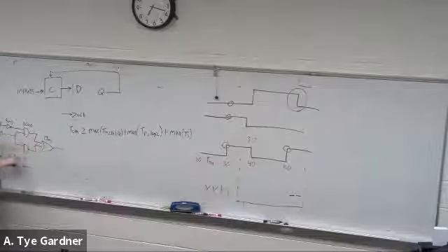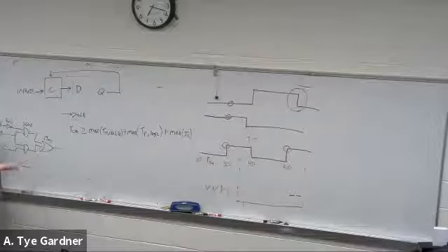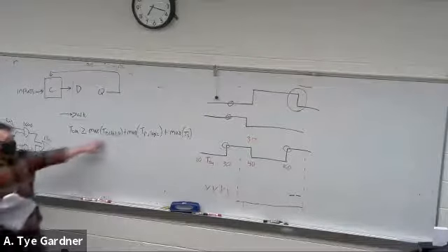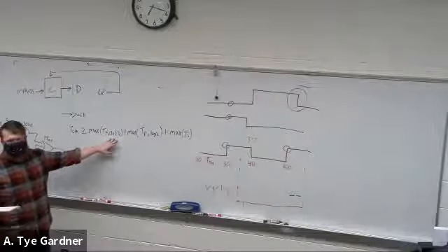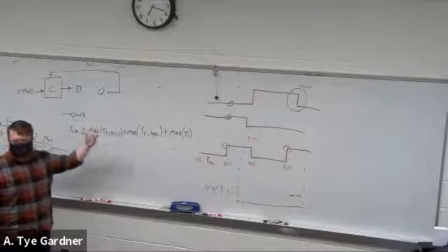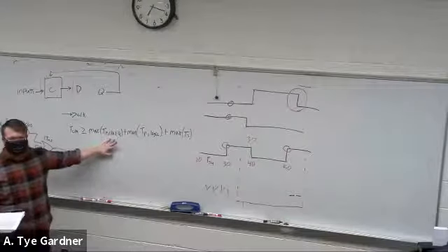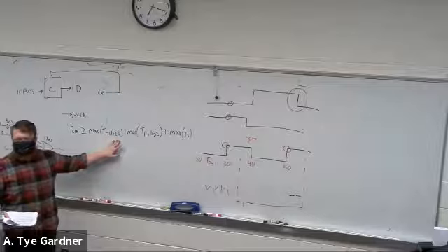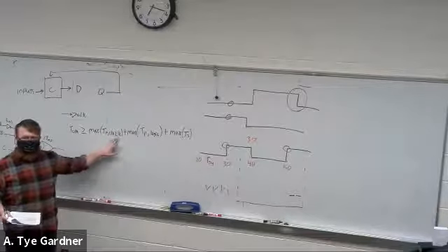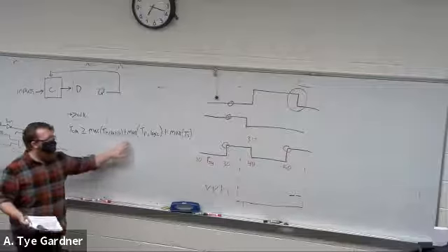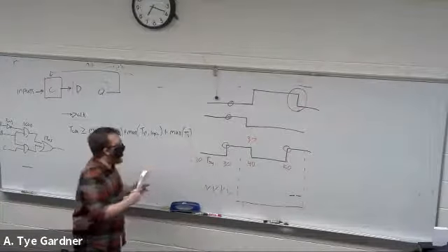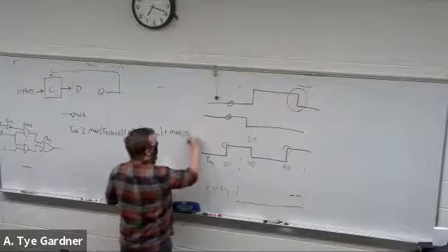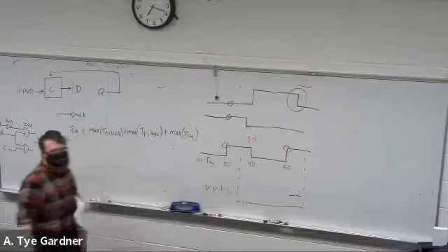I don't get to say it's faster because the C has a shorter. I have to deal with the maximum time. What is my worst case? That's the same thing as clock to Q, is what is my maximum delay? I don't get to take like the minimum, because what is my delay between 0 and 0? Well, it's none, right? Because it's already there. So what is my worst case? Because sometimes your delay will be different from 1 to 0 and 0 to 1. Plus the maximum setup time. So, sorry, the book has an S. I like SU because it's more clear, TSU.